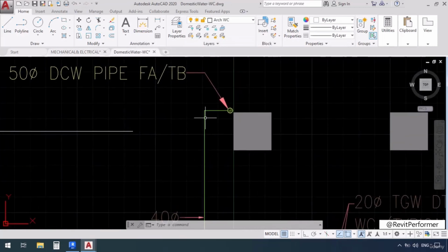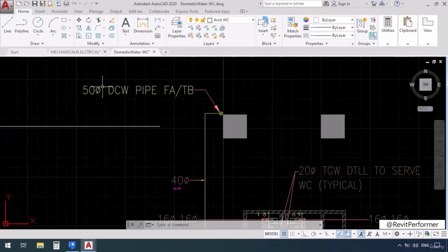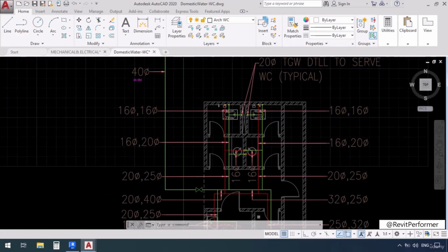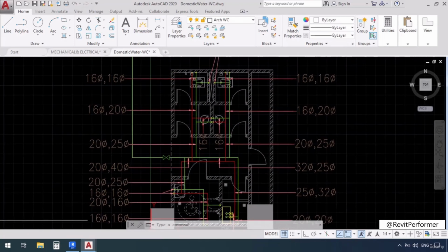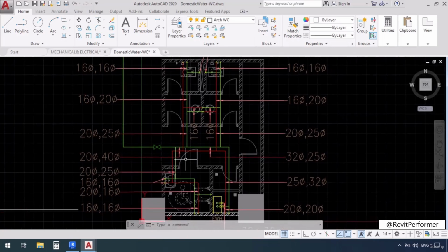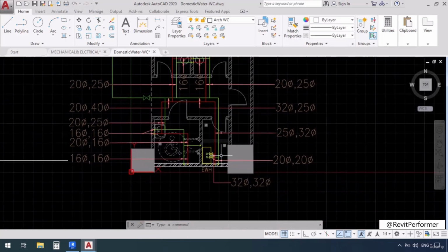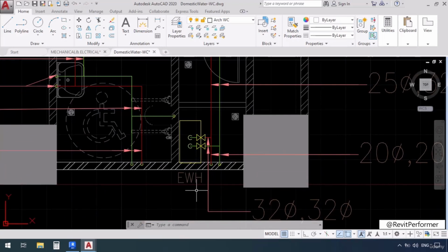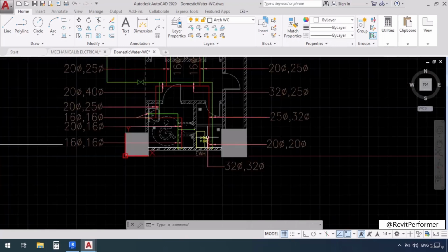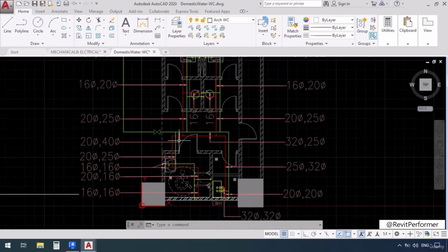Here we have a riser which connects to the pump house or the mechanical room, from which a domestic cold water pipe comes. So from that riser, the cold water enters the bathroom area. Then it gives these branches to connect to the lavatories. And after that, that whole pipe comes this way. Then it ends at this electric water heater. What happens here is that hot water is generated, the water is heated, then it's going to go this way to eventually end at the consumer.